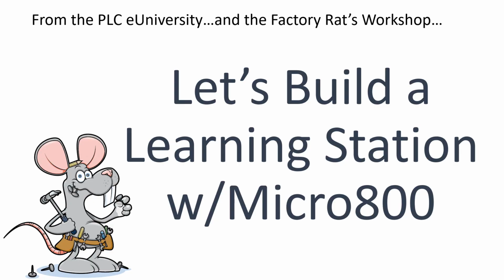From the PLCE University, from the Factory Rats Maintenance Workshop, let's build a learning station with the Micro 800. For those of you that don't want to use the simulator that comes free starting with version 12, release 12 of Connected Components Workbench, you can always build yourself a learning station with a Micro 800. My Micro 800 of choice is the Micro 820. The 810 is an entity all to itself. It's starved for features. It only has one COM port, doesn't have Ethernet.